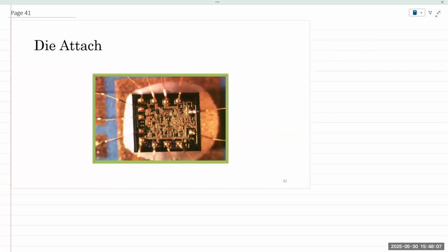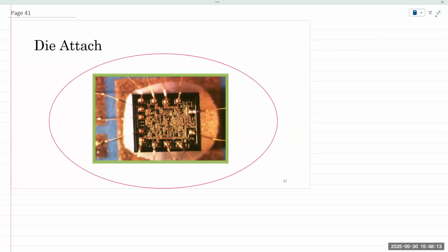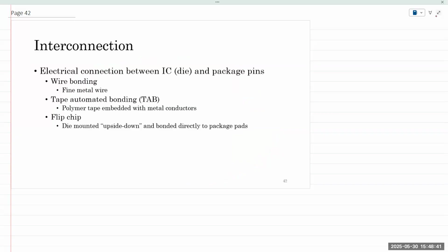And so the IC assembly flowchart, this is an actual microchip. The microchip is very tiny. There are gold bond pads. These are gold bonds, and these are gold wires that are coming out and making connection to big pads. So you have these wires coming out. The process of connecting those wires is known as wire bonding.